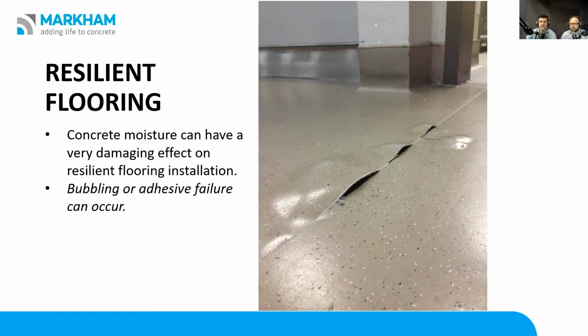So once we put these floors down, we obviously don't want any moisture coming up through the slab at that point. So what typically happens, if moisture is in the slab at this stage and can move freely through the slab, in this case we'll go with a vinyl. Say you put a vinyl plank down, the moisture underneath actually starts sweating with that heat that's generated from having a topping on it, and it'll bring it to the surface, and that moisture will start breaking down those glues. And in time, this can actually cause those glues to lose their bond, and then you have bubbling appearing, such as in this picture here.